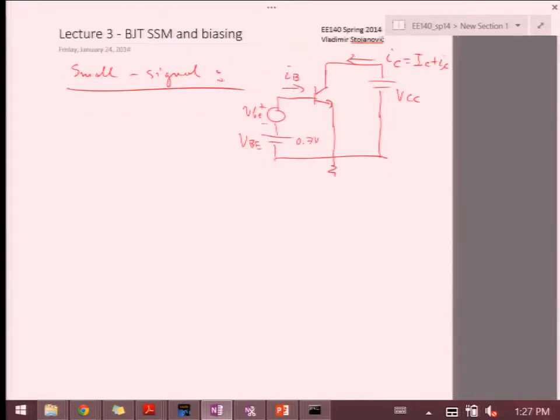If I try to describe the transistor as a 2 input ports and 2 output ports element, right? Because I have the base emitter difference, and then here collector emitter. Then I can in general represent the 2-port models through the following drawing.